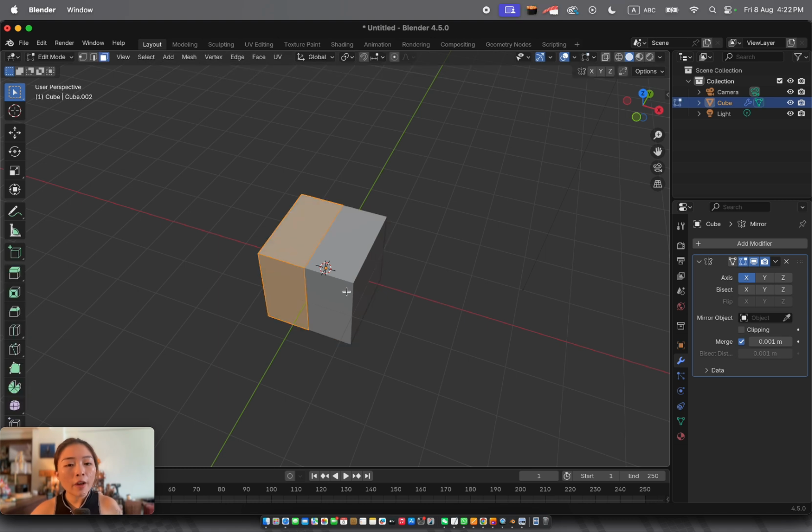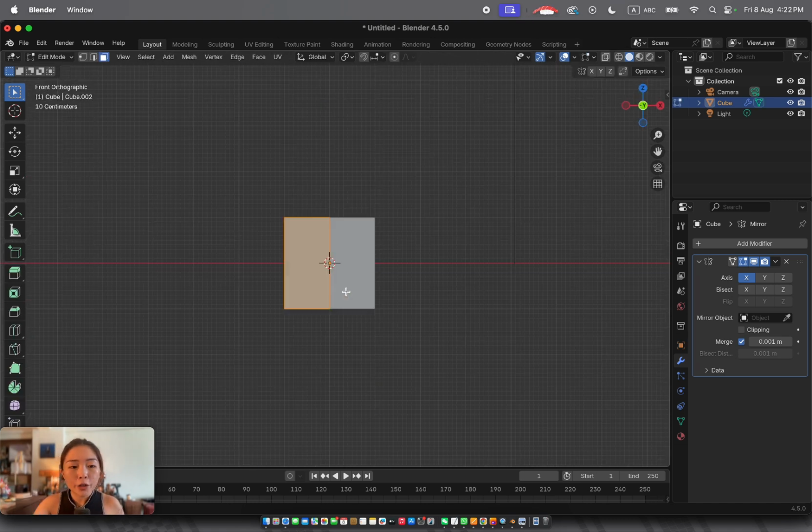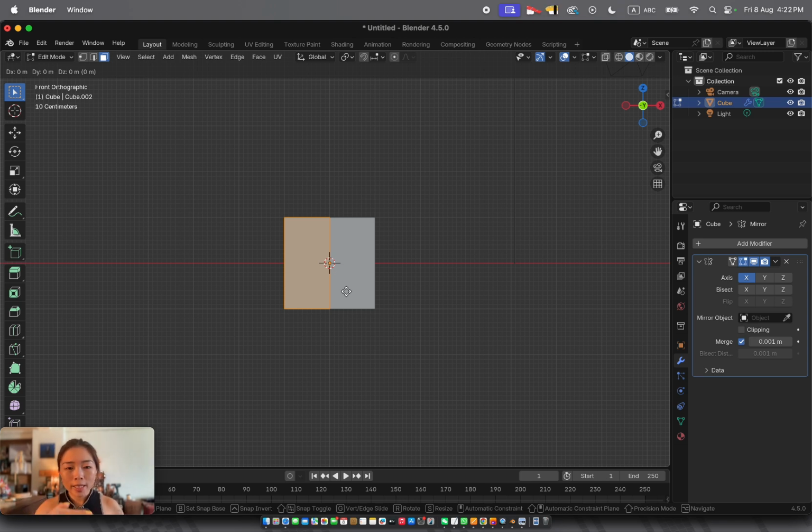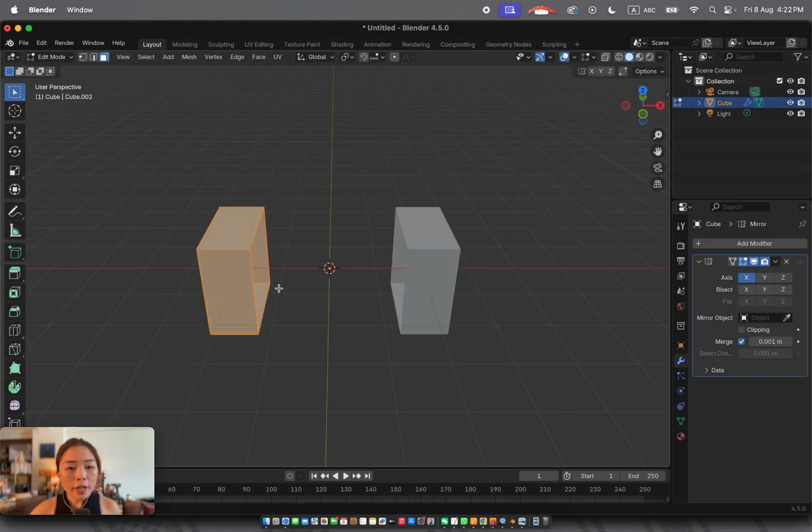For example, if I go to edit mode and select everything, which is half the cube, and move this cube by grabbing it, G, to the side along the x-axis, you see I am moving apart and the mirror mesh is also moved apart to the right-hand side. That is because we are taking the origin of the cube as the referencing point. No matter how far it is, the mirror is put at the center because I am putting the origin right at the world origin.